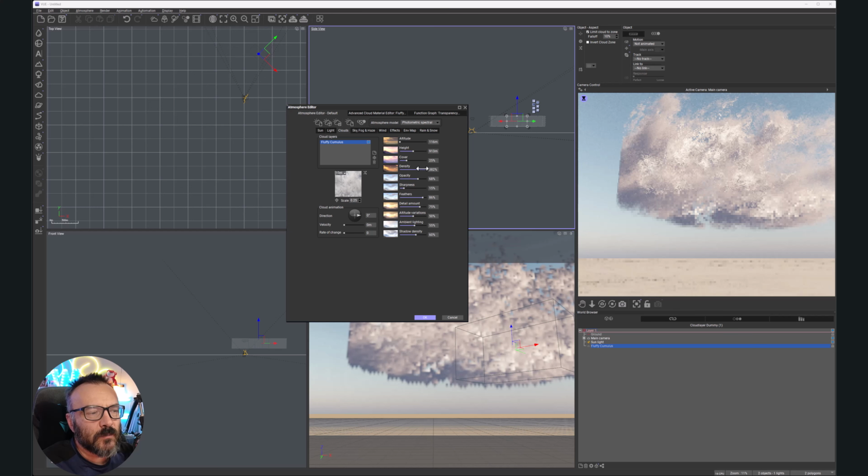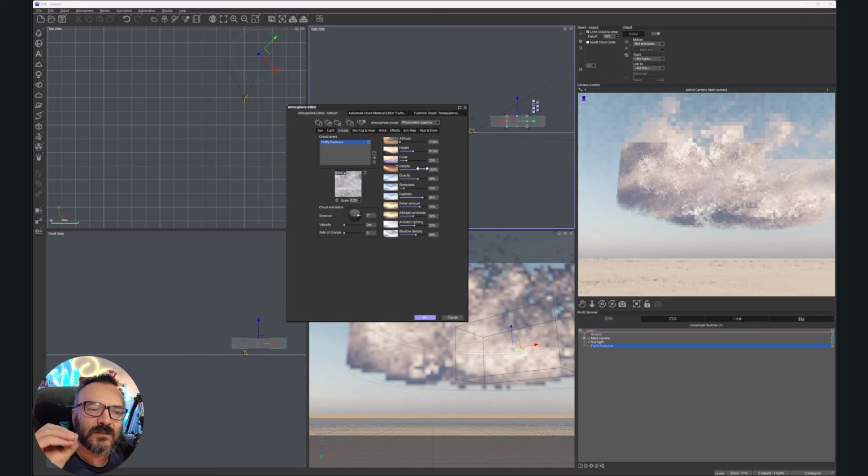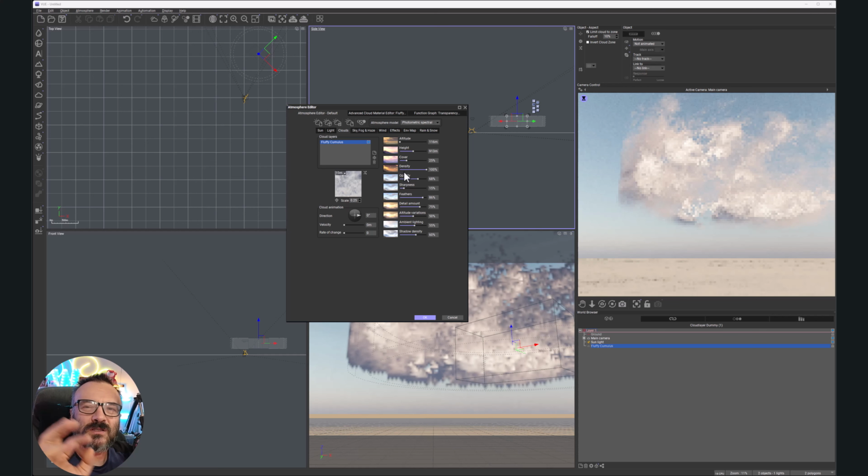It will take a little bit longer, but I like my density a little bit lower because I think it creates a better result for light to pass through, more fluffy. It's a personal preference, but this is what I usually do. In some cases, I put the density at 2-3%. I just want something on the sky, an uneven sky, because that's what it is in reality, and that is what this creates for us.